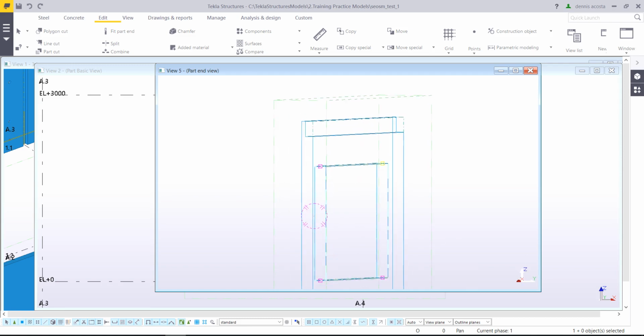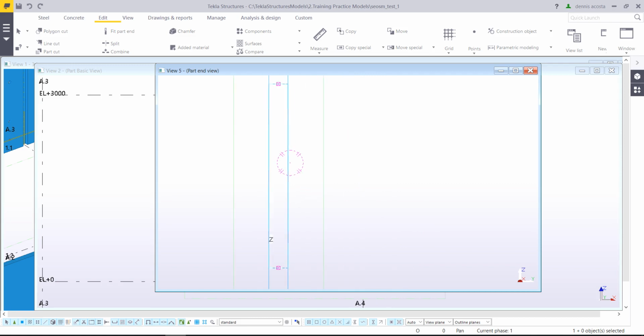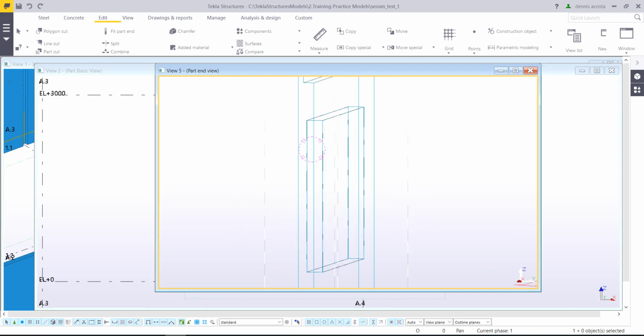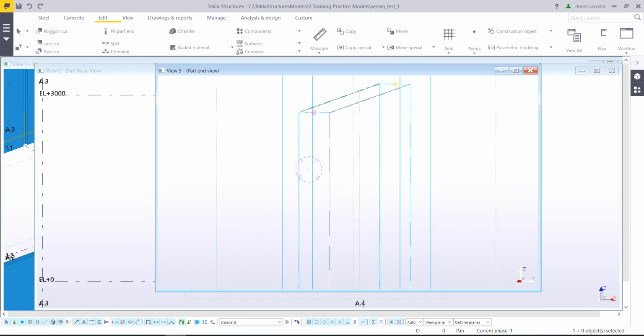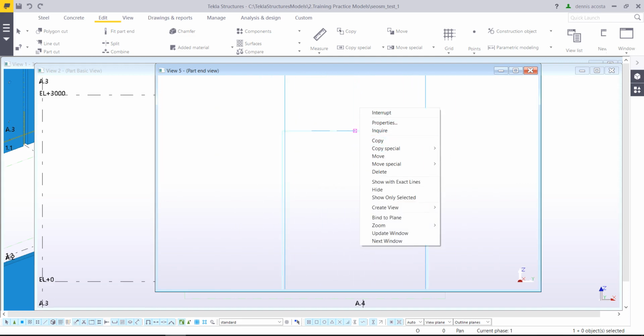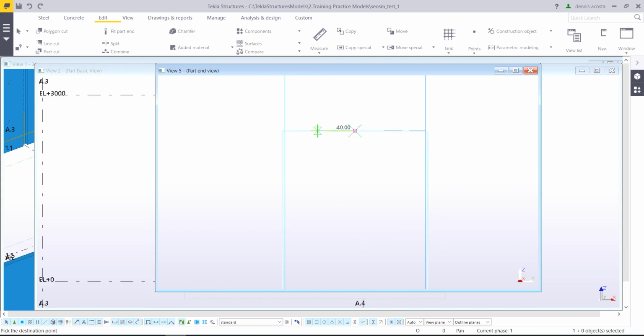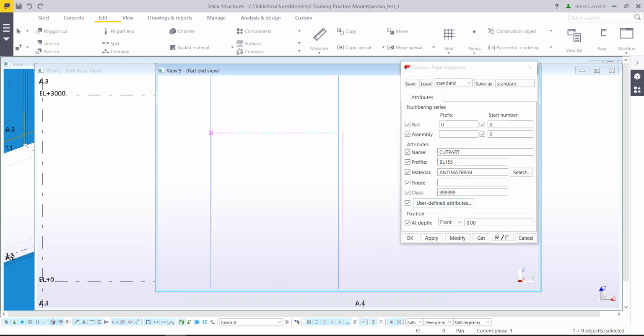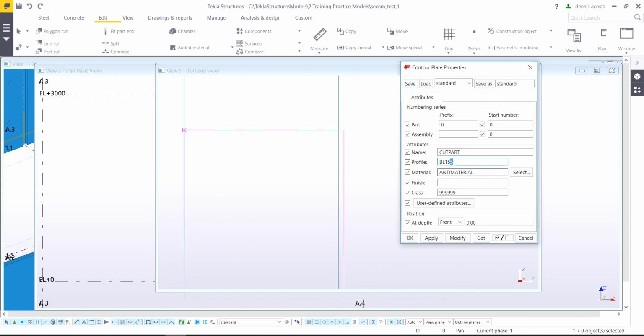this cutting, okay, I need to move this one to the surface. It's very important that your handle is at the surface, right? Because that's where the binding starts. Okay, so I'll change this one to front, modify, and then this one 150.